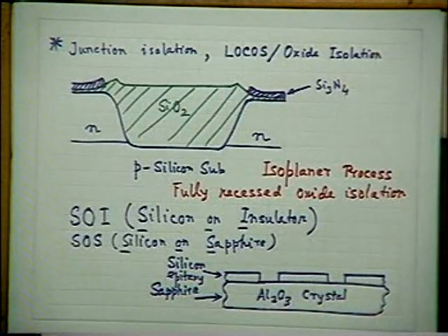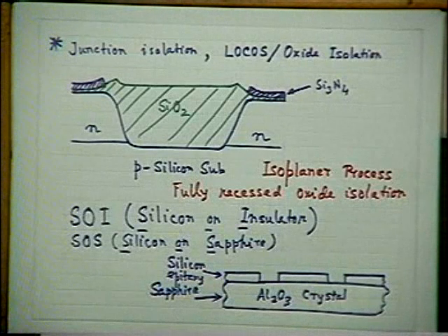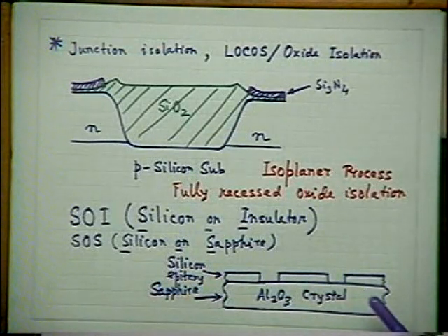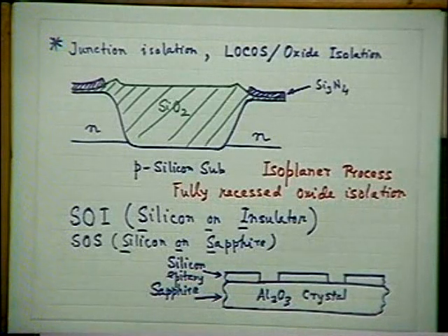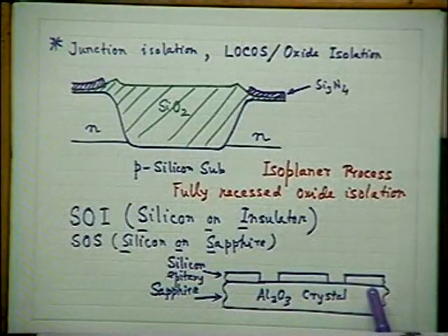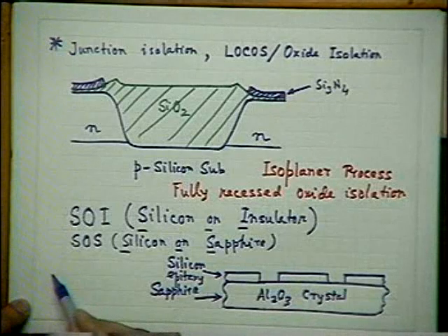So these things ideally should be able to go to very high frequency and high speed, depending on whether it is an analog circuit or a digital circuit. And this is a very advanced thing. Unfortunately, silicon on sapphire came with a great promise. But ultimately, if you review papers, all recent publications within the last 5 years, you do not find many papers on SOI, SOS. The reason is it is technologically very tough. And the quality of the silicon film, which is grown by a process called heteroepitaxy, the process used is called heteroepitaxy.